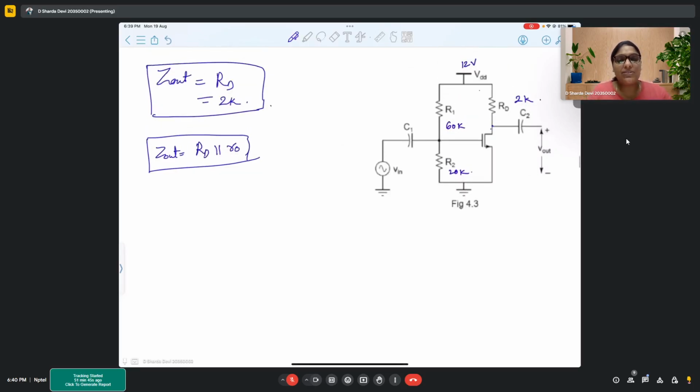So when you simplify your circuit into the small signal model, it's very easy to analyze the things further, because all of these are very evident from that small signal model. That's why small signal models are formed. There you can simply connect all the resistors the way they look in the circuit and analyze them properly. It will give you a better understanding of the circuit.